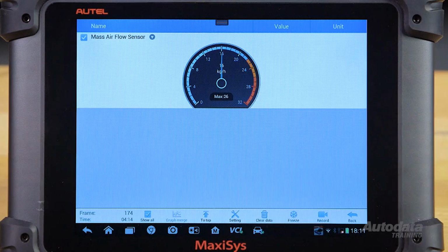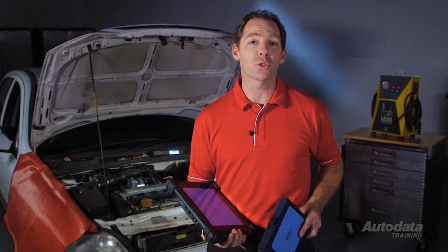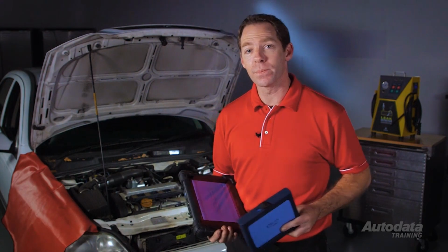Remember, a petrol engine should run very rough or stall, and a diesel shouldn't. If the data values did not change significantly and the engine did not stumble, then we need to check the control circuit. Using a scan tool and oscilloscope is the best way to test the EGR valve control circuit quickly and efficiently without the need for valve removal.